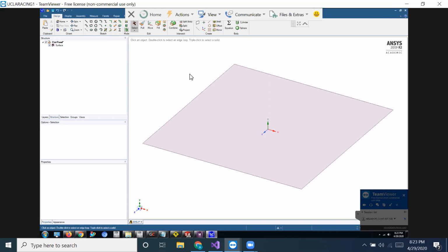The way we can do that is by splitting up the geometry. So for example, let's say that you have a mounting hole. Typically around mounting holes, the stresses tend to be higher because it's a circle, it's a hole, and holes tend to be stress concentrators.